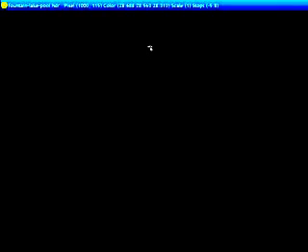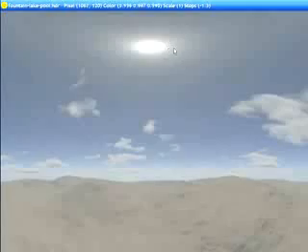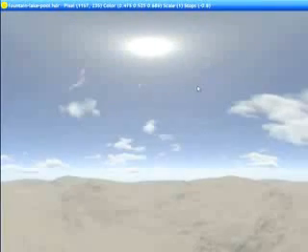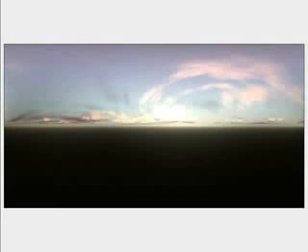Depending on the type of HDRI that you use, the HDRI itself may or may not be suitable as the background image in your scene. This image that I'm in right now would really not be suitable as a background image because it's too bland and too washed out, although it does a fine job as an HDRI. And here are a few HDRIs that would work well as backgrounds in a scene. They're obviously spherical images, but the important thing is that they just look good and they have nice vibrant colors. Using a different background image than the HDRI that you use in your scene is perfectly fine. The only important thing you need to remember is to find a background image that matches or fits the illumination provided by the HDRI that you use.